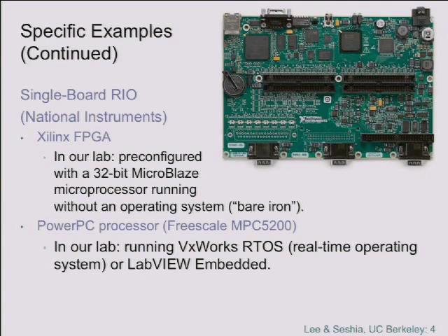systems. Writing low-level code that directly controls the hardware with no intervention from an operating system. Writing code that is mediated by an operating system, where the operating system gives you certain conveniences like being able to talk to the network. When you're running on bare iron, you could say, well, gee, can I telnet into this thing? No, you can't, not unless you write the code to handle the telnet connection, okay? But if you're running on an operating system, there might be support for that.